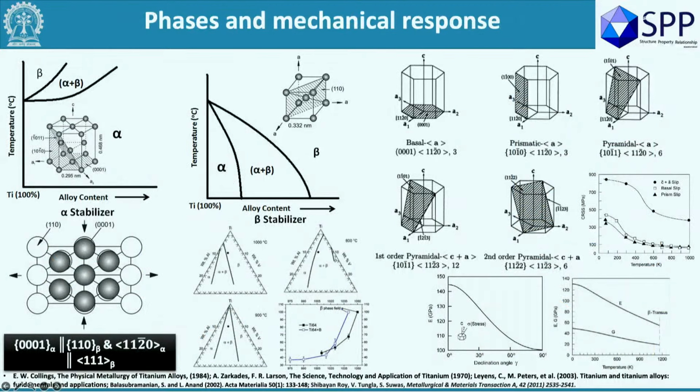Okay, so that's fine. Titanium in general appears with an HCP alpha phase. We call it alpha phase, HCP, and it transforms to the beta BCC phase at high temperature. Now these two phases are related by crystallography, and I will be talking a lot about the crystallography of this. That's called the Burgers orientation relationship. The black box, that's what the Burgers orientation relationship is.